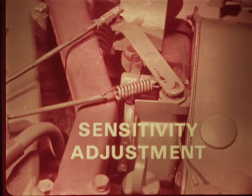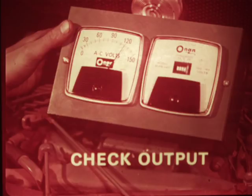The final engine adjustment is the governor sensitivity adjustments. This changes the spread in RPM between no load and full load operation, and also may take out any roll that the power adjustment didn't correct. Factory settings, however, seldom require adjustment. To make the adjustment, move the spring toward the pivot shaft for more sensitivity to reduce roll, or away from the shaft for less sensitivity. After a sensitivity adjustment, it's also important to recheck the no-load and full-load output settings again.